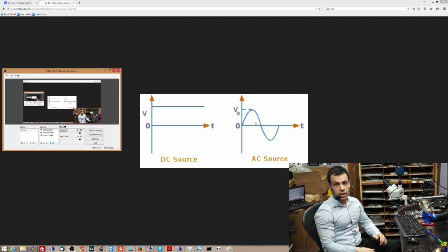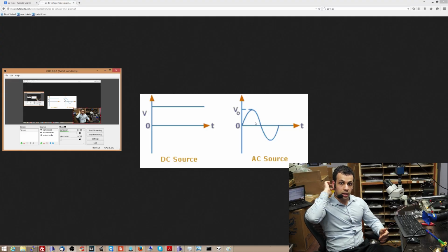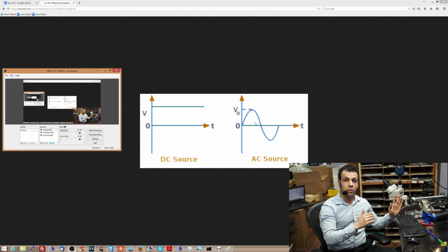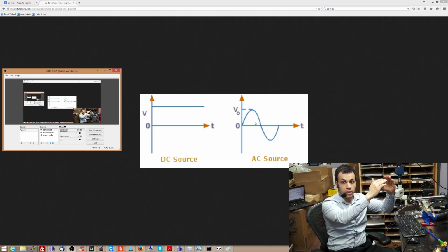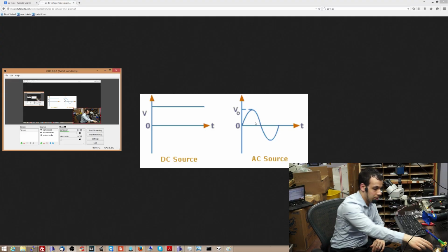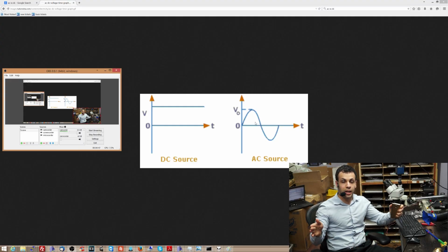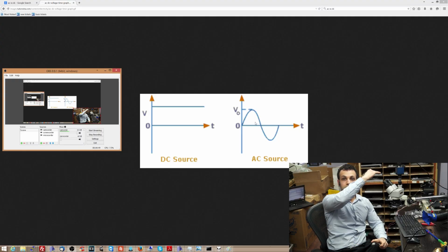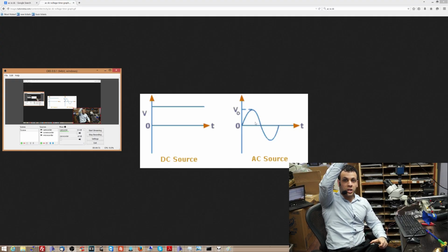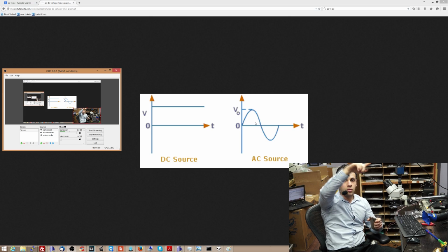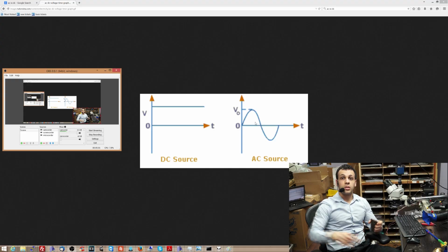Now, the same thing could be said for, let's say, a musical amplifier. The way my amplifier works is you take an input signal and it wants to modify a bigger signal to create the output signal. So let's say I take the tiny signal out of my cell phone, I plug it into the amp, and then I get a big signal out of the speakers. What it's doing is taking a really high power level and modulating it based on the tiny one. So it's turning this high power, let's say 70 or 80 volts, into a waveform for my speakers based on the 0.5 or 1 volts that comes out of here.